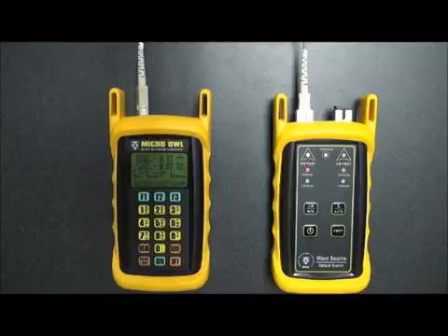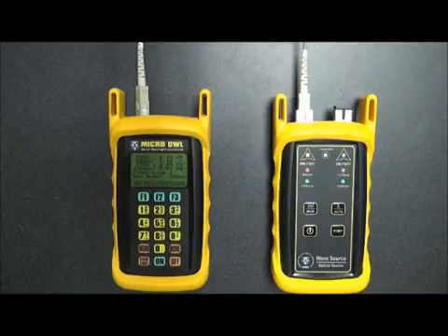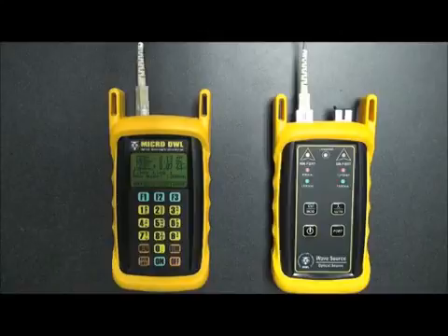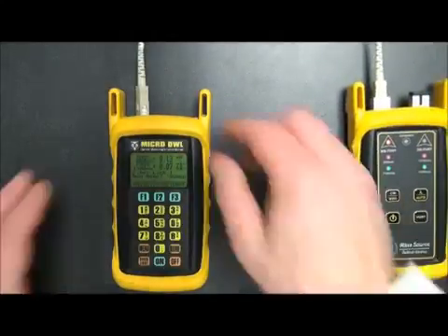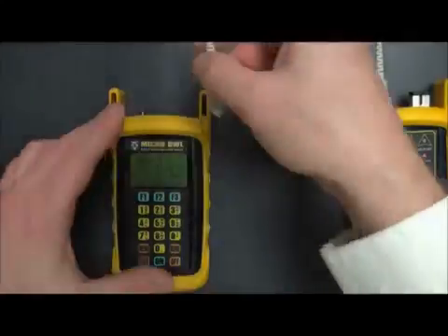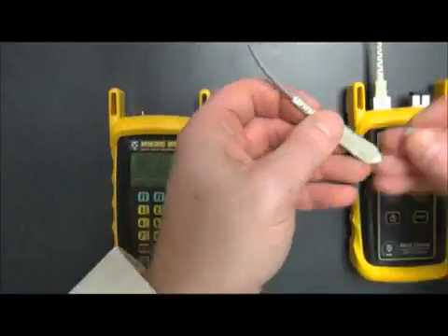So once we've verified that we've set up our equipment, we've verified that everything is zeroed out correctly, it's time to take readings. Okay, now that we've zeroed out all our equipment, we've set it up for the test that we're going to be doing today, it's time to take readings. Now, in order to take readings, we simply need to take the light source to one side of the link under test. As you can see here, we'll do that. And we can disconnect from the power meter to do so.